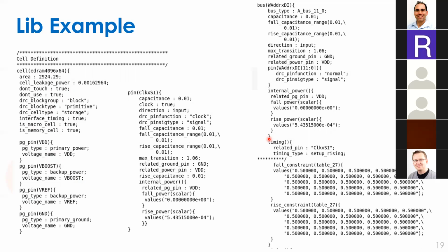So Slava, what you're saying is that a macro provider should make a file like this for each corner, and it's basically a lot of work. So maybe the approach should be like what Odem and Robert did, include some huge margin that will be used as a safeguard. Yeah, so that's exactly what I did. I simulated on all the corners with different temperatures, and I just took the worst case, and that's what I detailed here. It's suboptimal, but it's too much work otherwise.